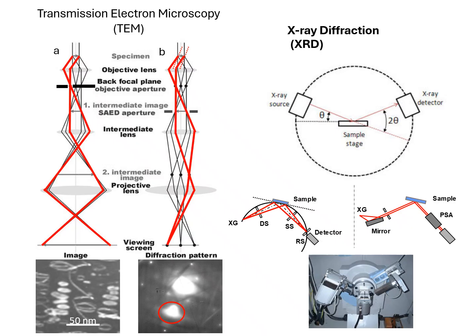So this distance here is proportional to the inverse spacing of the atomic planes in the crystal. And it's a very useful method for navigating around in orientation space, for tilting the crystal and understanding where one is, and for setting up particular diffraction conditions to give you information about the microstructure.